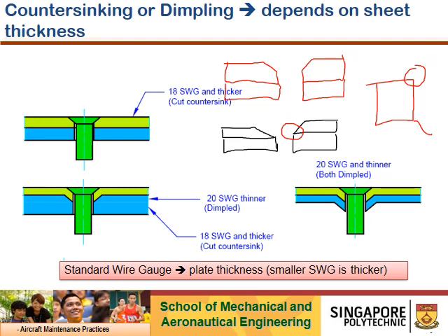We call it a knife edge. If you do a stress analysis, you will realize that a sharp corner here is a local stress riser, where your failure point will start, and cracks will propagate because of the sharpness.